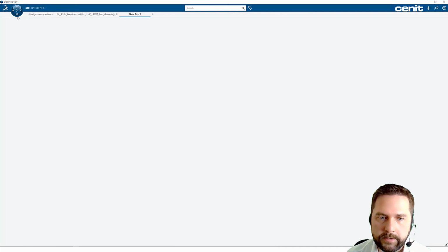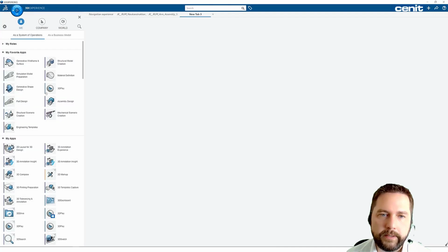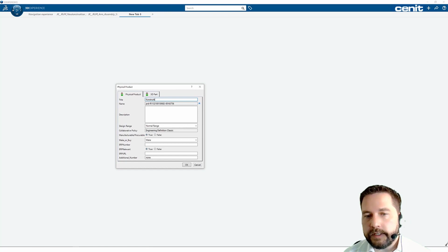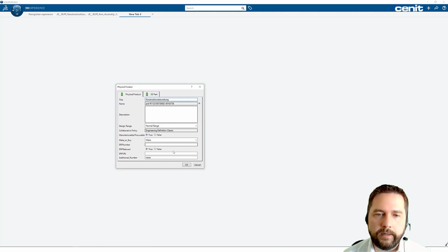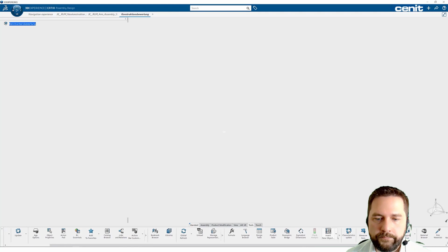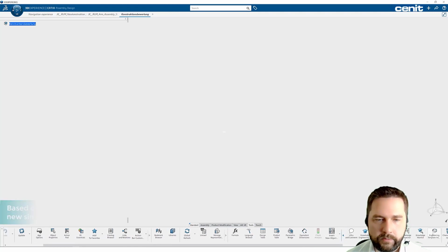And now the question is if this is still sufficient or if we maybe have to change it again. So now the designer can use the template which was prepared by the simulation expert in advance and put his new version of the model into this template. All the mesh settings, all the boundary conditions, everything will be automatically set to the new model, and also the solver settings and so on.